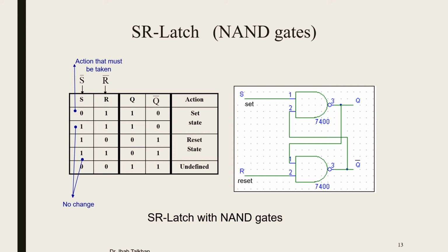So actually here, in order to have the SR latch with NAND gates comply with the definition of the NOR gate, we have to use S bar and R bar, and this will make us change some of the design of the NAND gate latches, and this one I'm going to discuss with you in the next slides, because everything here is opposite.